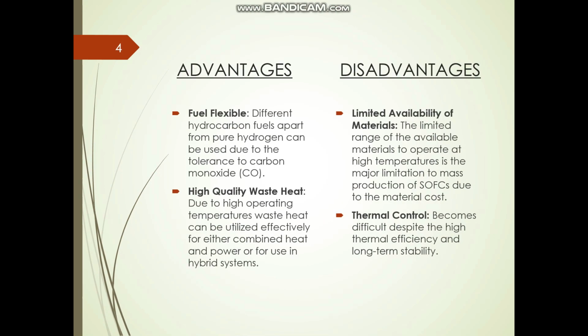Comparing SOFC with other fuel cells, they are attractive in the sense that they are fuel flexible, as a variety of hydrocarbon fuels can be used since they are CO tolerant, which means that voltage loss occurs only at high carbon monoxide concentration. Also, these cells are advantageous as, due to higher operating temperature, waste heat is of high quality and can be utilized for further heat and power generation.